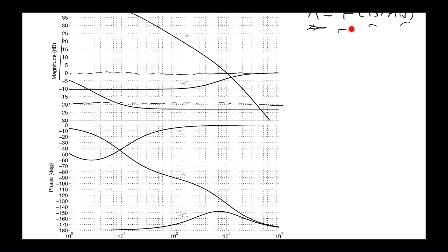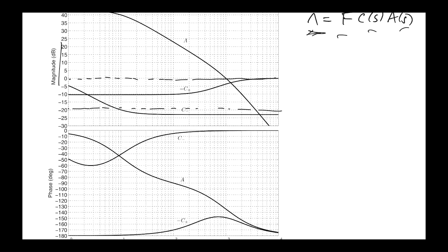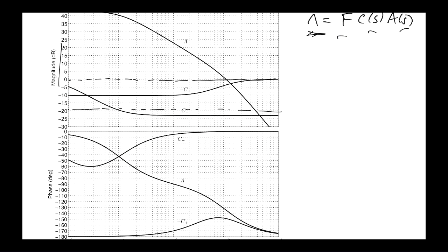In addition to that, we have F, okay, which is the resistor divider network. It's always a number between 0 and 1. So when F is 1, it's just this line here, right? Which means on the log scale, you're just adding 0 to whatever the loop shape is. But if F is, say, 0.1, then it'll be down here and it'll bring everything down, okay?